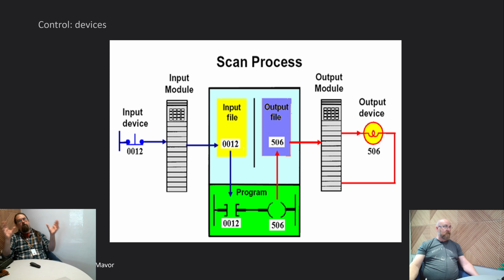So you may have seen a diagram similar to this, but at the top level, a PLC is broken out into four distinct areas. We have our input side, and we have our output side, and then in between that we have a bunch of stuff that is internal to the PLC. That is our logic and our state tracking for inputs and outputs, essentially.